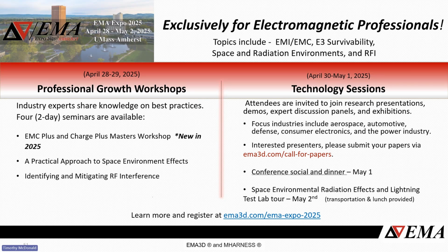It has EMI scanner and tools that can very rapidly assess potential problems early in your product design with very low effort. EMC Plus is a 3D simulation tool that can also model printed circuit boards, but also 3D components as well as cables connecting to them. And so EMC Plus is different. We can consume exports of boards from SI-Wave. We can also consume fields from SI-Wave if we choose to do so, but they are independent products.